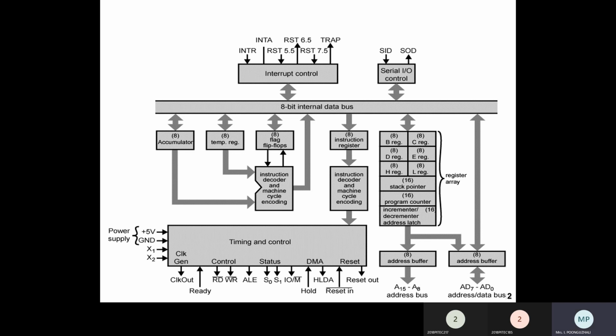Program counter, I think you know what the program counter is. Program counter is a register which stores the address of the next instruction to be executed. For example, while writing a program, we'll have an address location and we'll be writing the instructions. To those instructions, we'll be writing the opcode. If you have a microprocessor program, we'll be having 3 columns. The address column, and then we'll be writing the mnemonics.